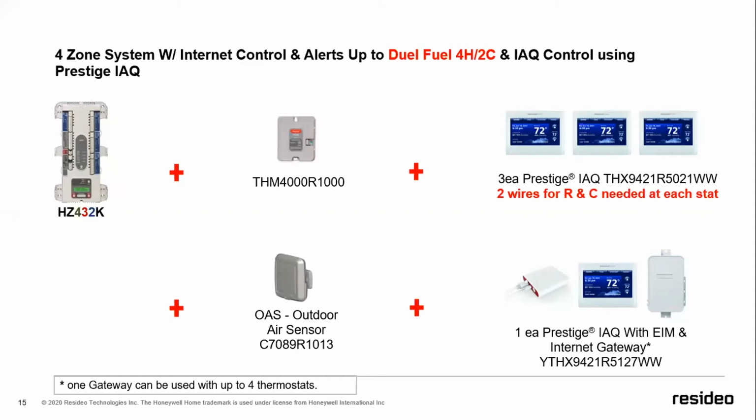Okay, but here's the thing about it. We do have to have 2 wires going to the subbase of that thermostat, because that gorgeous color screen that you can set up with any color combination that you please would be too significant of drain on just some batteries. So we've got to have 24 volts, but here's what I want you to understand. It can be 24 volts from any source whatsoever. It does not have to come from the zoning panel. So this gives you additional flexibility.